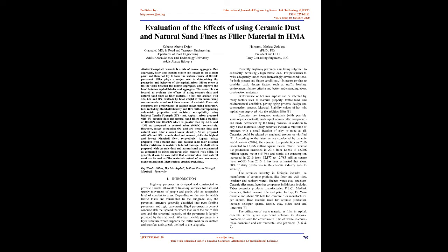For pavements to resist adequately under these increasingly severe conditions, for both present and future, it is necessary to consider basic design factors such as traffic loading, environment, failure criteria, and a better understanding of construction materials. Performance of hot mix asphalt can be affected by many factors such as material property, traffic load, environmental condition, paving, aging process, design, and construction process. Marshall stability values of hot mix asphalt can improve with the addition of filler [1].